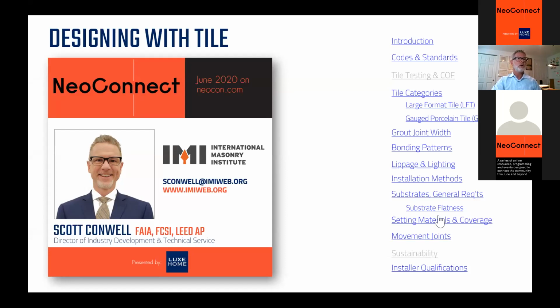What are the FF and FL levels? Eric wants to know. Floor flatness and floor levelness numbers associated with the requirements for large format tile. So good question. FF and FL, those designations are from the ACI test. That's concrete speak. And it's important to understand a little bit about concrete. So the higher the FF number, an FF of, I think, 65 is considered a super flat floor.